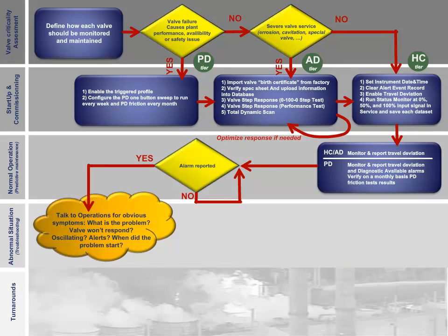Talk to operations for obvious symptoms. What is the problem? Valve won't respond? Oscillating? Alerts? When did the problem start?